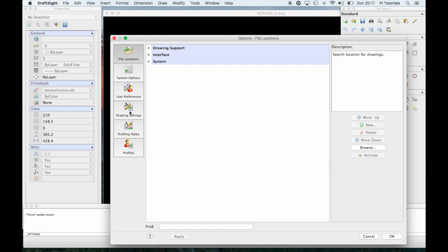So I use it for when I'm designing laser cut items, and I just find it very accurate. You can type in your dimensions. I'll take you through it all, but that's the reason I use it. It's very similar to AutoCAD, and it's very accurate, whereas in Inkscape you can type dimensions in, but I find particularly on circles that the dimensions you type in is the size of the bounding box, and it's not actually the size of the circle, which is very frustrating.